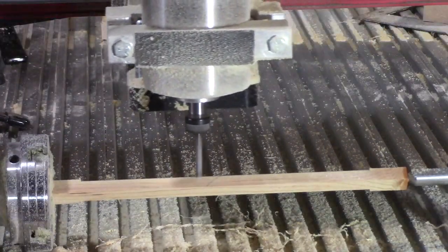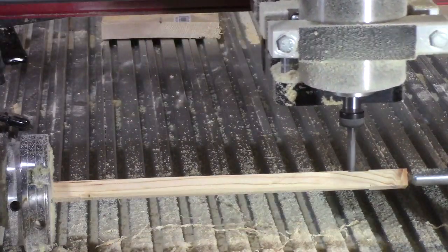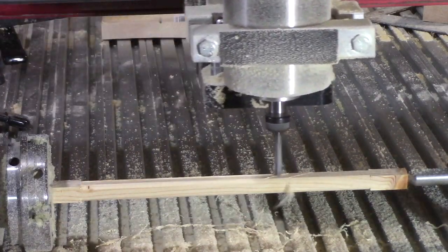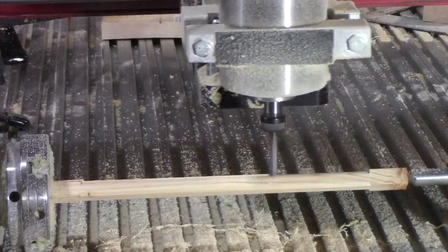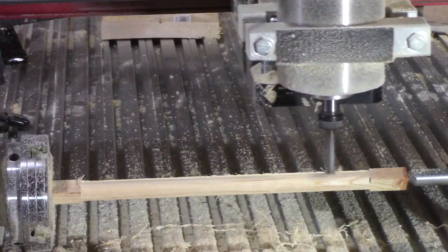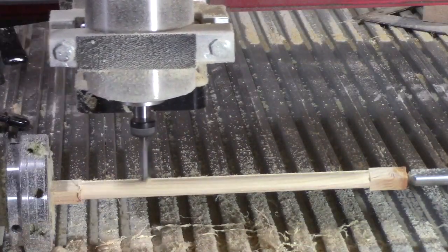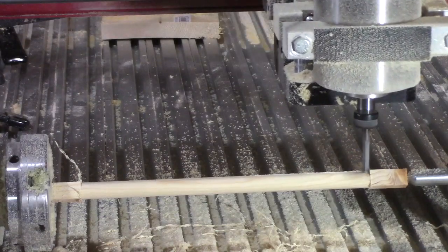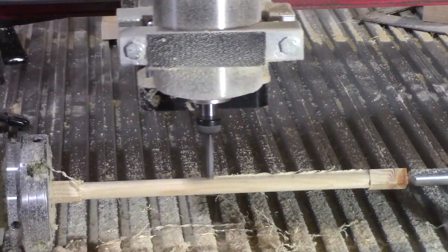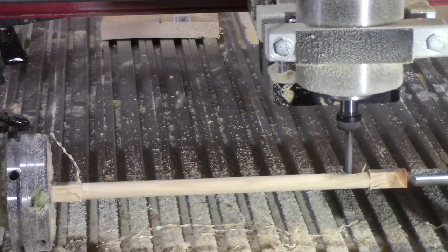I found that if I cut from right to left instead of left to right, the vibration is less because as I come across, it's more firmly held on the left side where it clamps in there. So I rearranged the way I actually cut it. What I did is instead of having all 8 of those grouped as one and let it figure out where to start, I grouped them individually and did the first one on the right first, and then I made 8 separate ones.